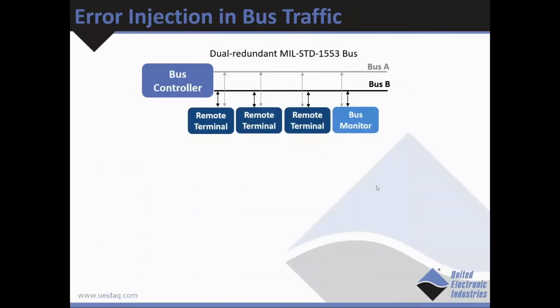We just discussed in the previous slide sending commands and receiving status messages. The picture here represents a 1553 bus upon which the messages travel. In a 1553 system, standards are expected to be met. Timing must be adhered to. If data arrives early or late, it's an issue. If too many or too few words arrive, this is another issue.